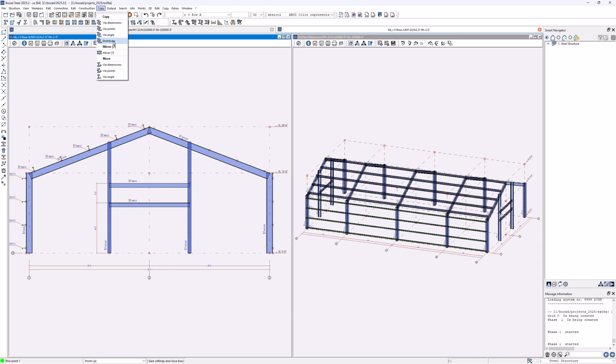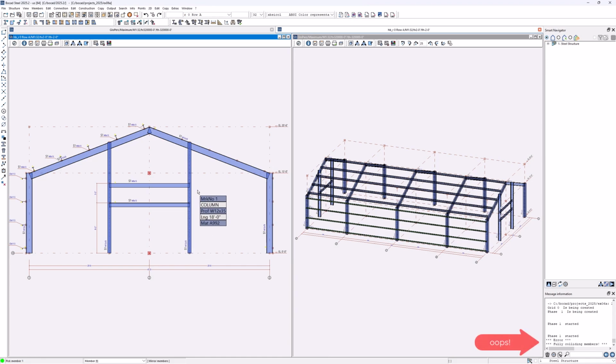Now, if we have a purlin or a girt with all kind of connections on it, we finish the connections, then it might be worth copying, but here it's still a stick model, so we don't have to use the distribute yet. What can be useful at this stage would be a mirror again to select the various components there, and we'll mirror that over the central axis.